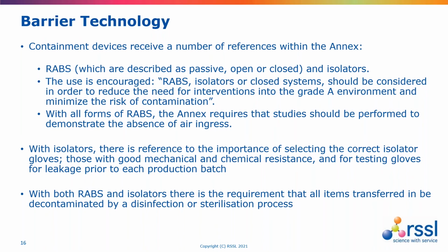There's also important emphasis that even though we might be using isolators for sterile product manufacturing, we need to ensure that product and indirect non-product contact sites are sterilized independently of the decontamination process, and that is due to the fragility around hydrogen peroxide, which is the most common means of decontaminating the space, and that's linked to distribution, the fact that it doesn't penetrate, and due to some of the variations that appear from cycle qualifications and the use of biological indicators and so on.